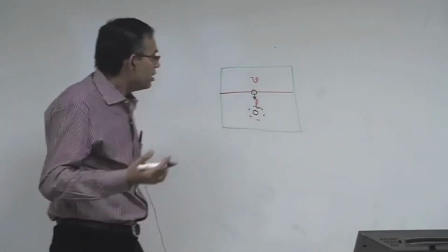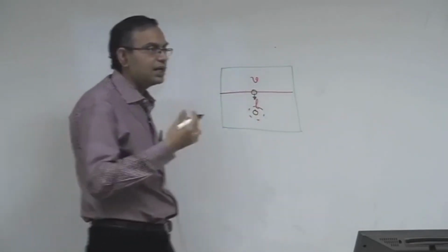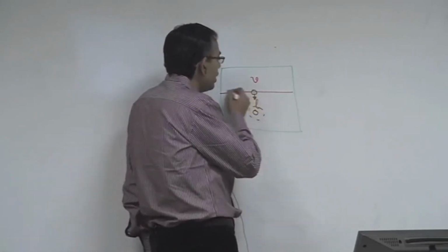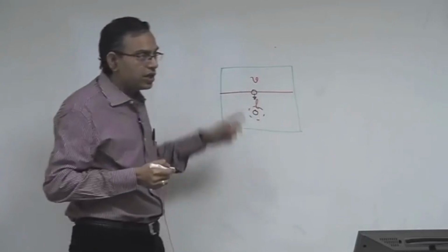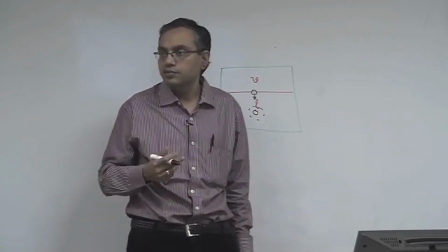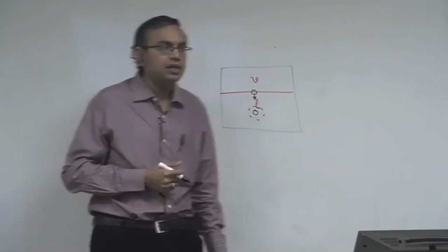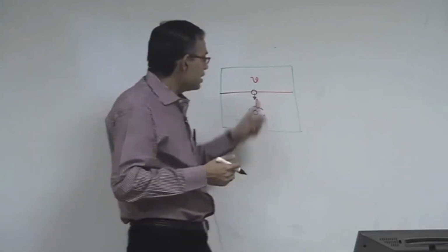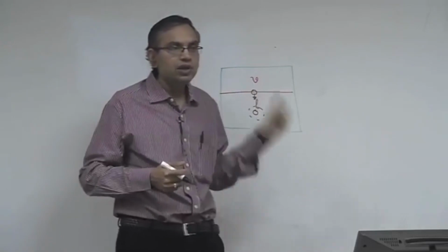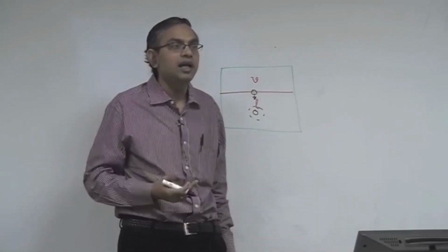Now, not only that, typically this energy is expressed like this. When you have an interface, because of this reason the interface is considered to be under some tension, and this state of the interface is described by a force which is also called surface tension, and it is expressed in terms of force per unit length.